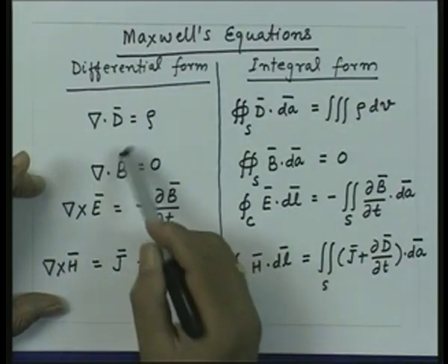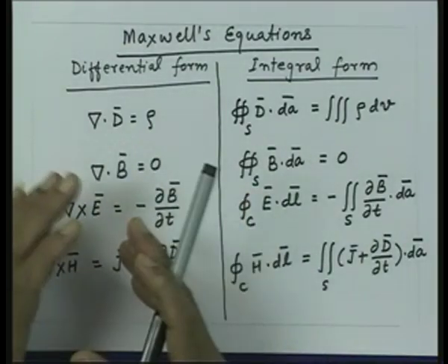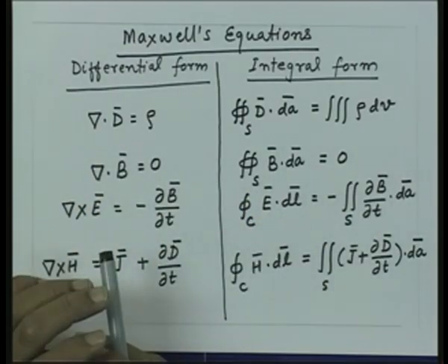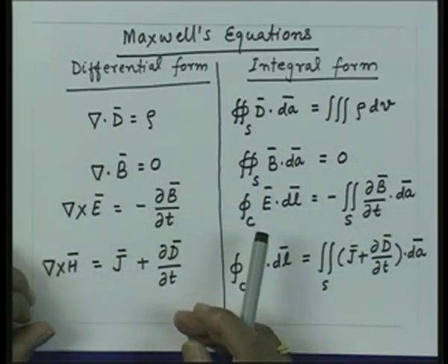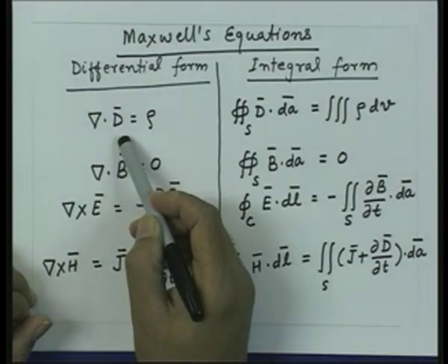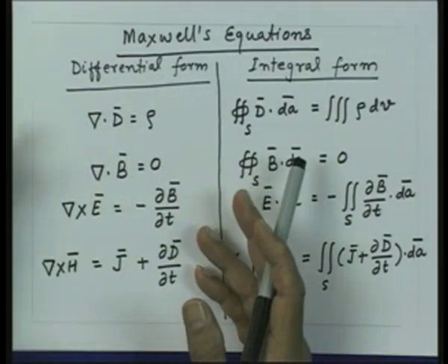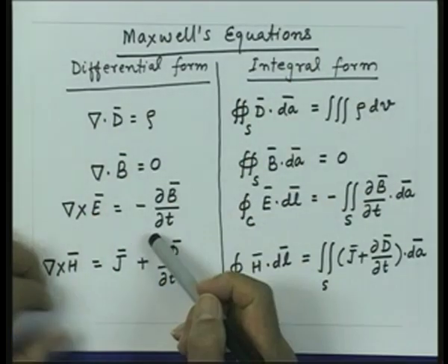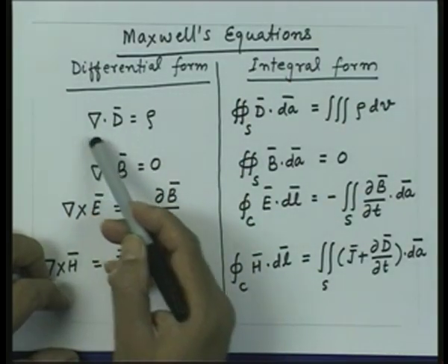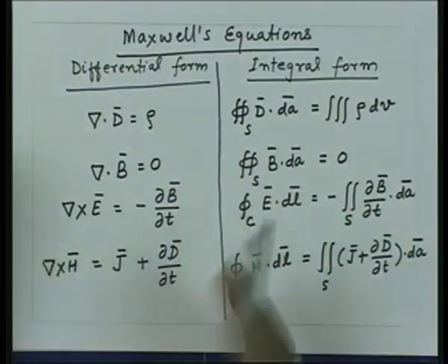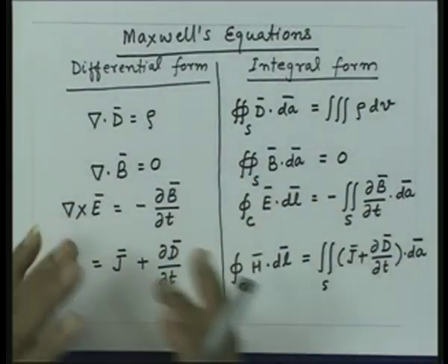Depending upon whether the permittivity or the permeability of the medium is varying as a function of space, that means if the medium is inhomogeneous, I will use this equation. If the permittivity is constant as a function of space, then I can write the same equation as we saw earlier. I can take epsilon out and say del dot E is equal to rho upon epsilon and so on. So, you may have various forms of these equations depending upon the conditions applied to the medium, whether we are dealing with the electric field, magnetic fields, or the displacement vector and the magnetic flux densities and so on.